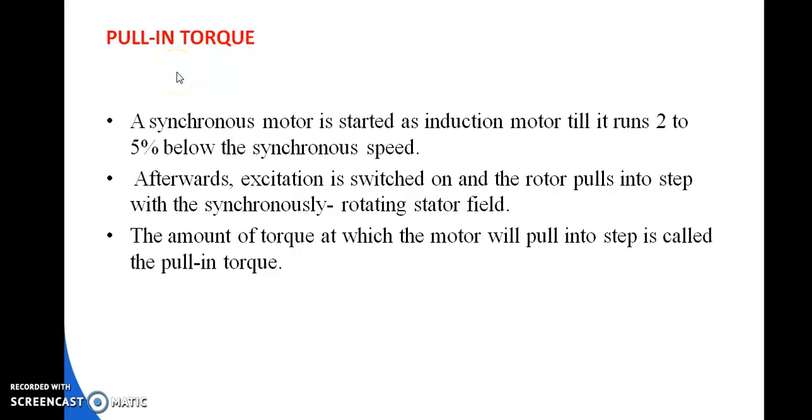Third one is your pull-in torque. A synchronous motor is started as an induction motor till it runs 2 to 5% below the synchronous speed. Afterwards excitation is switched on and the rotor pulls into step with the synchronously rotating stator field. The amount of torque at which the motor will pull into step is called the pull-in torque.